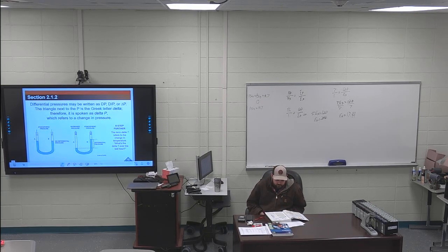Manometers. 221, first sentence of 221 is highlighted. The basic principle of operation of a manometer is that a column of liquid of a certain height exerts a specific amount of pressure. The immediate next sentence is a separate highlight. Liquids commonly used in manometers include mercury, water, and certain types of oil. Water, I think, is the most common.